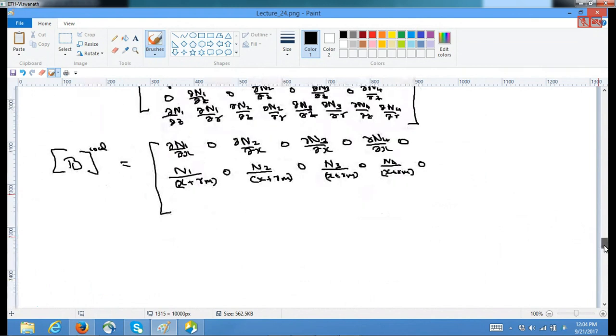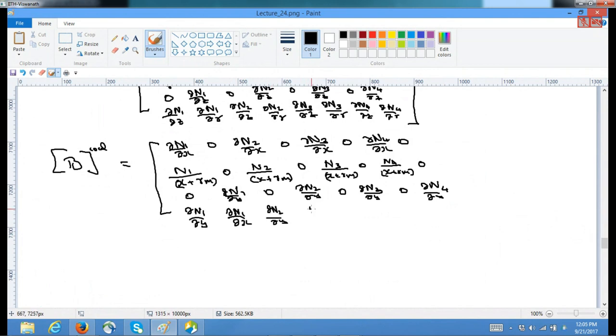Then 0, del n1 by del y, 0, del n2 by del y, 0, del n3 by del y, 0, del n4 by del y, and this is del n1 by del y, del n1 by del x, del n2 by del y, del n2 by del x, del n3 by del y, del n3 by del x, del n4 by del y. This is our B matrix for the axisymmetric case.